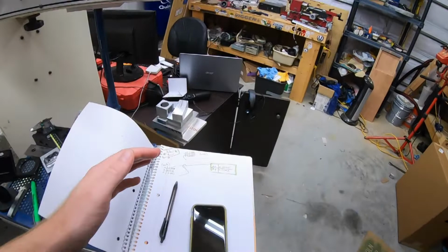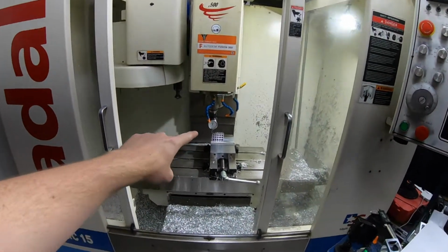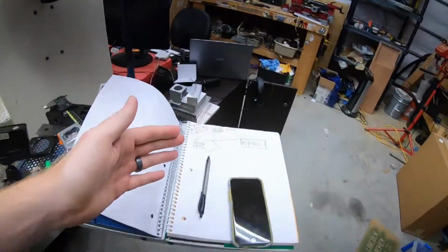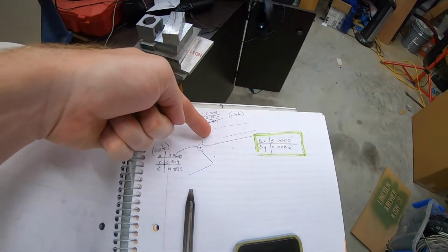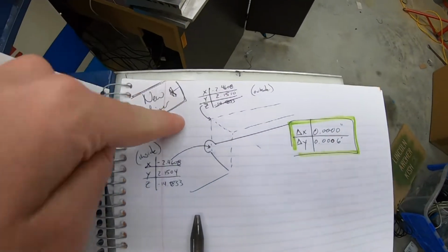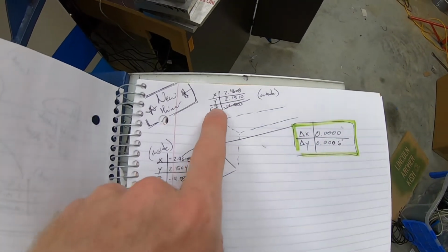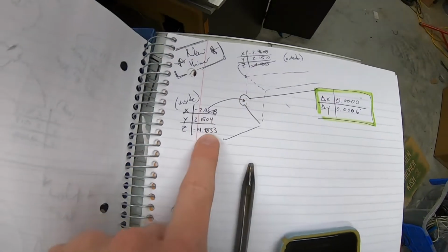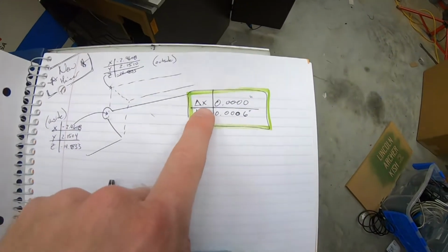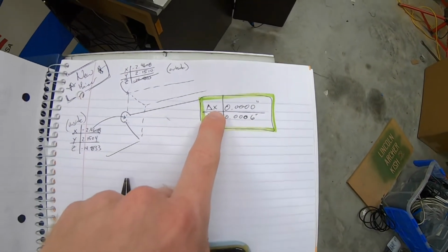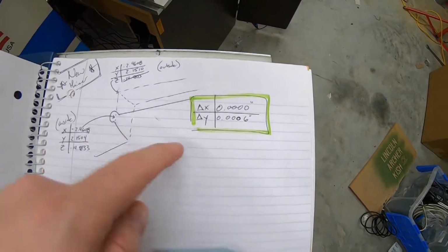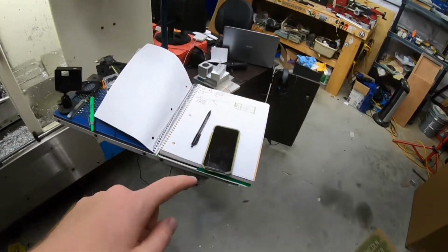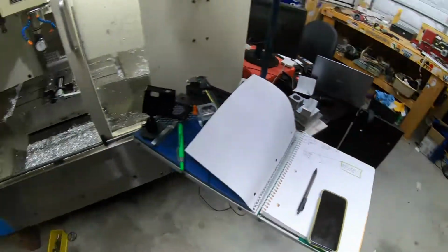Who would have thought, if you don't crash your inspection tools or your probe, you'll get good numbers. Probe the outside of the 1, 2, 3 block. Probe the inside of that corner. I got my fixture offsets. I only did the X and the Y. The Z I didn't reset. You'll see that they're the same numbers. But total deltas, X was spot on for the outside corner and inside corner, and then the Y was off by 6/10. So I'm very pleased with all that.